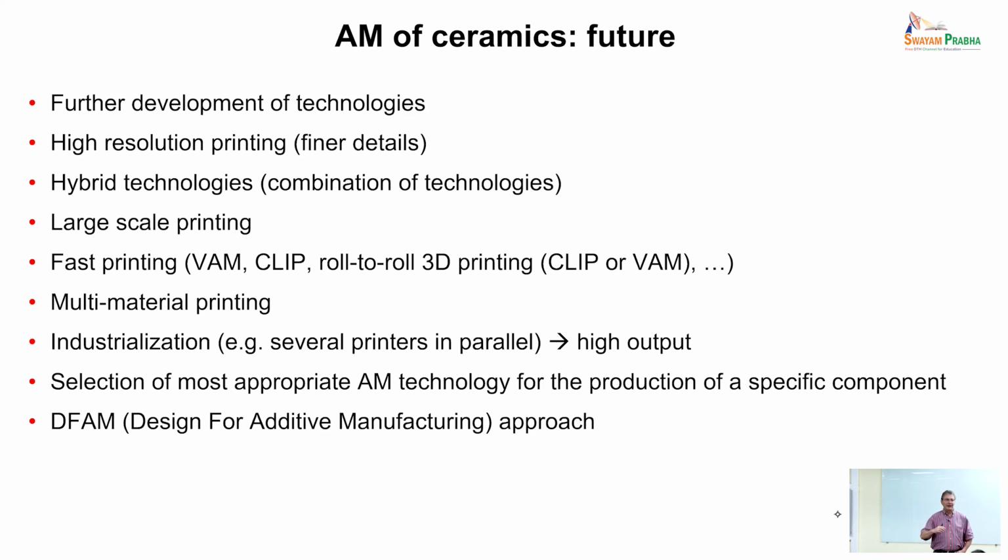So you can have the optimization simultaneously, for instance, of strength and permeability. And you can embed also an analysis of the tortuosity of the flow channels in order to optimize, for instance, the making of chemical reactors or filters.